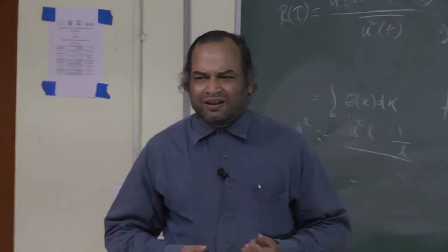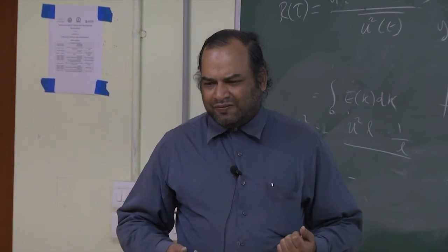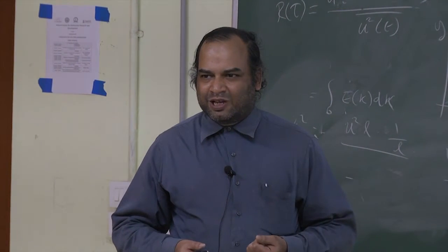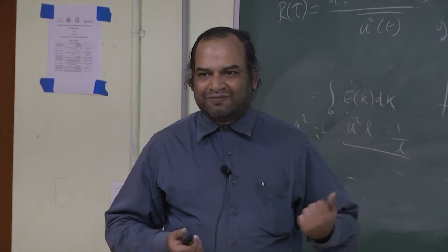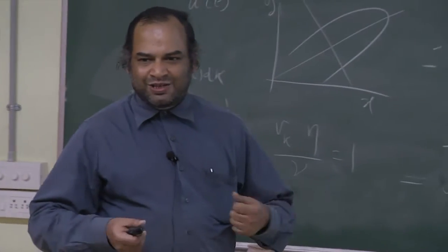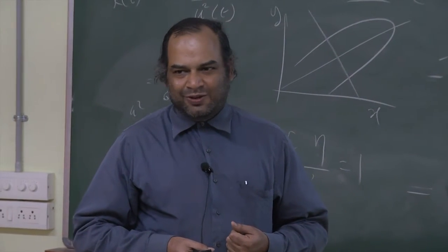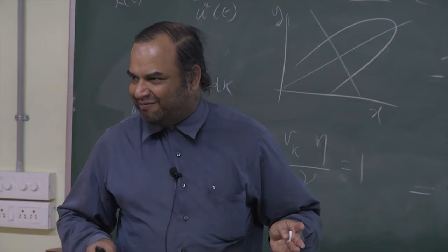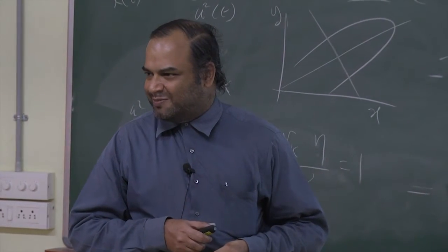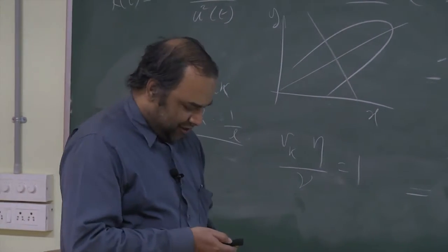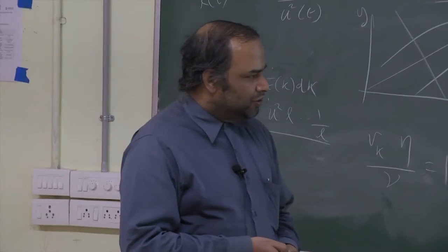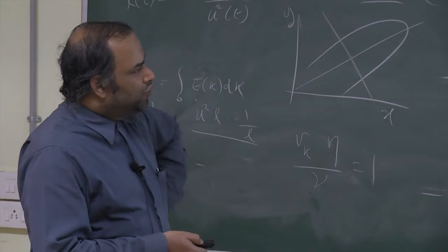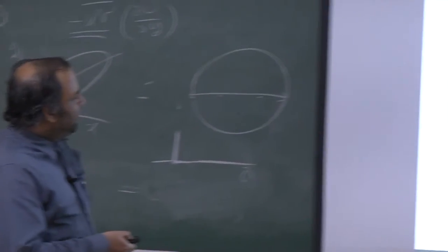So with hot wires, there are things like calibration drift and all that. If there is time, I can tell you about some of the things we have battled with. We have also built our own hot wires, and I must tell you, it's absolutely whimsical. But that's the best we have for time-resolved measurements. Okay, so if I have occasion, I'll tell you more of that. So typical hot-wire probes will look like this.